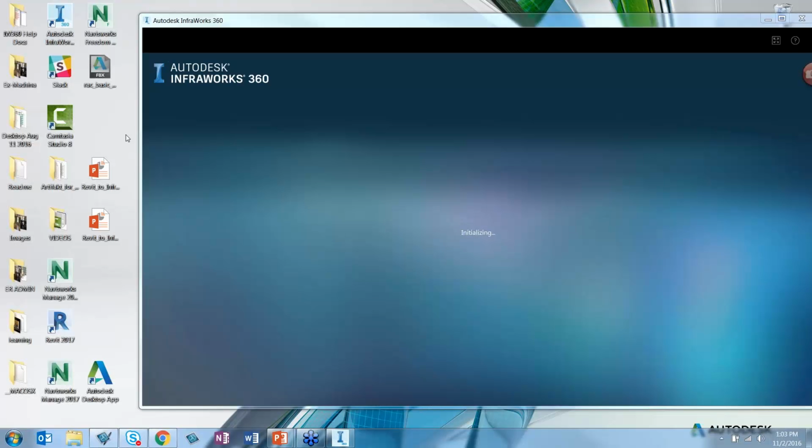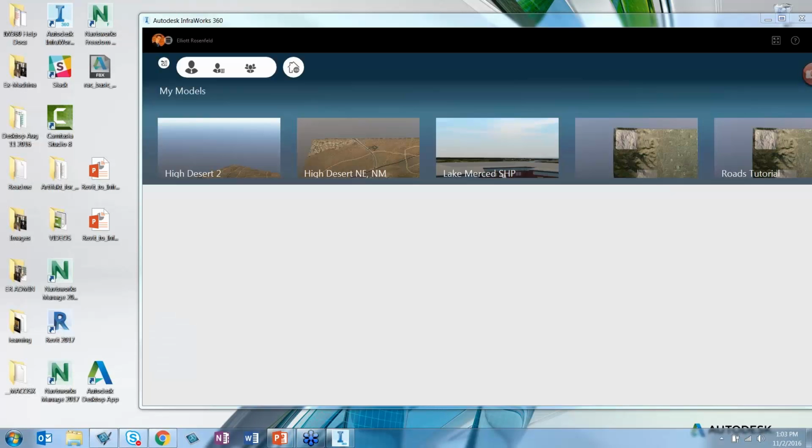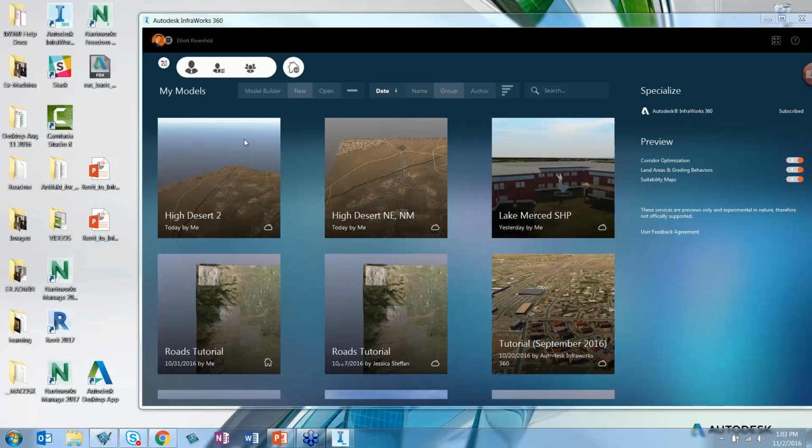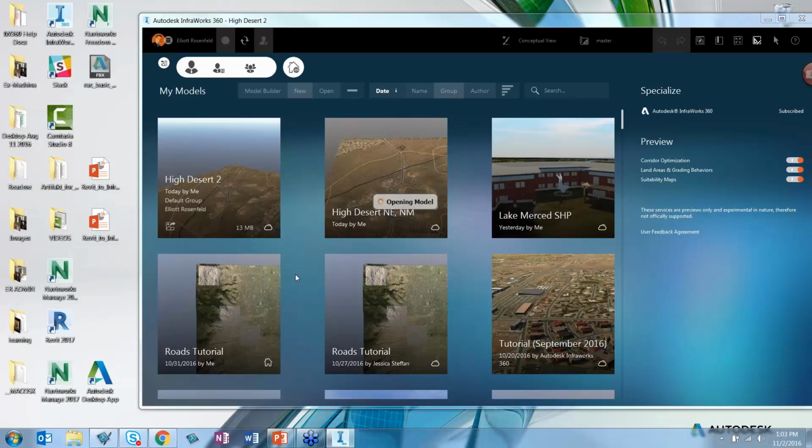Yes. And a couple of your comments here. I was moving a little quickly. Instead of using a point of interest in a script to load your latitude, longitude, and elevation, you can also use the status bar in InfraWorks, which is at the lower left corner of your screen. Which is another good way when you're bringing in an FBX. Again, I rushed through that, maybe not satisfactorily.